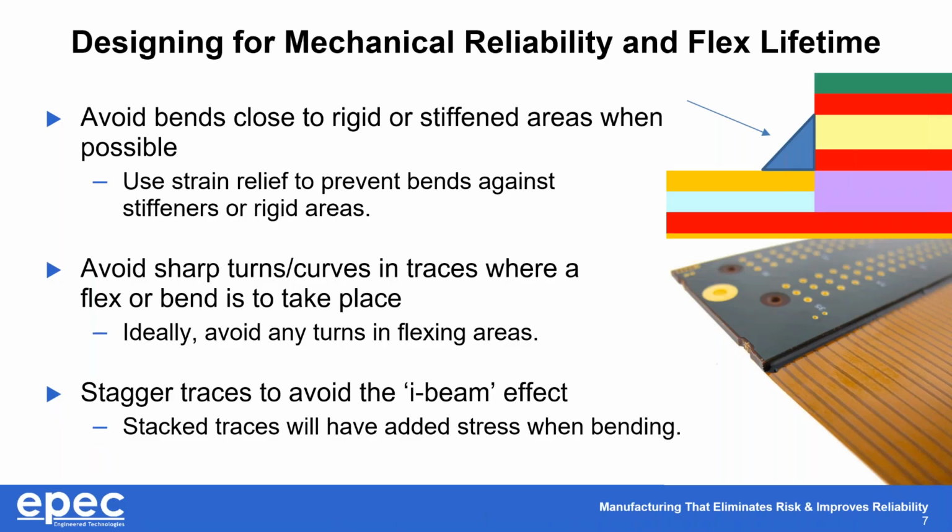From there, for traces, you're also going to avoid what's known as the I-beam effect, which is where traces are directly above and below each other. This is a common effect that has been touched on many times in many presentations, and it's just a simple change to stagger traces, to prevent that added stress whenever a circuit's bent.